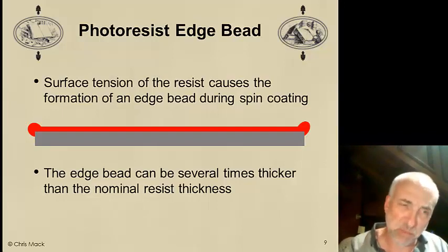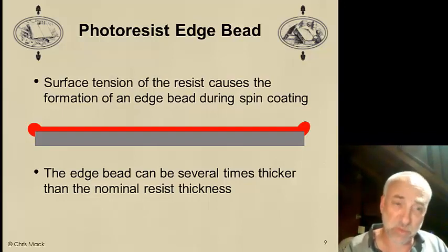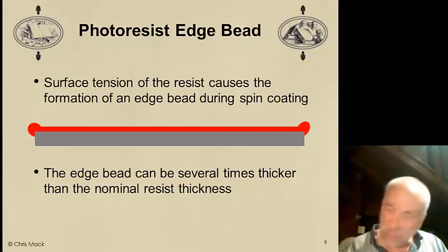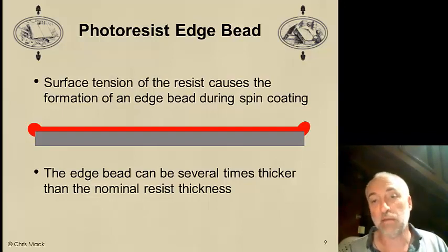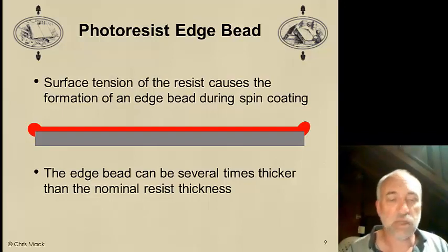Pretty simple, conceptually, a simple process. We take great care at the uniformity of the airflow and the temperature to get the best thickness uniformity of this spin-coated material, but the results are phenomenally good.